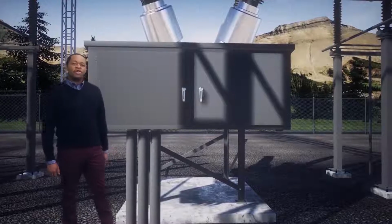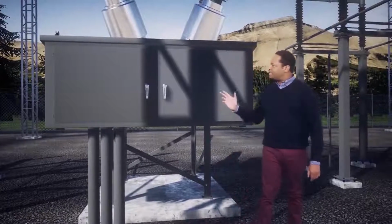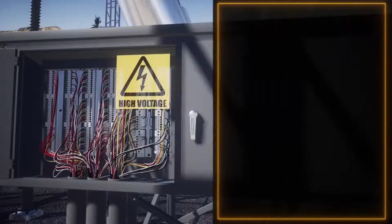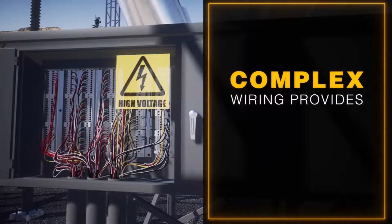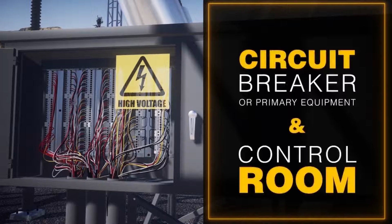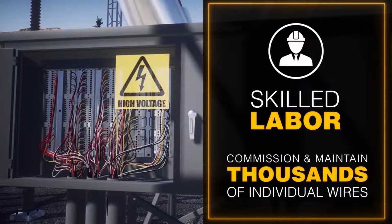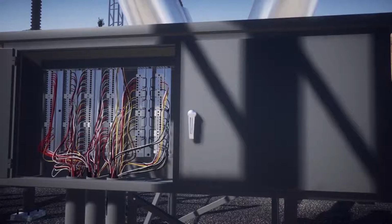Here we are at a circuit breaker control cabinet, and this is where we can begin to build our process bus. You're probably familiar with this complex nest of wires that provide signals and measurement data between this circuit breaker and the control room. Consider the skilled labor required on site to commission and maintain these thousands of individual wires. Now, let's convert these analog signals to digital.